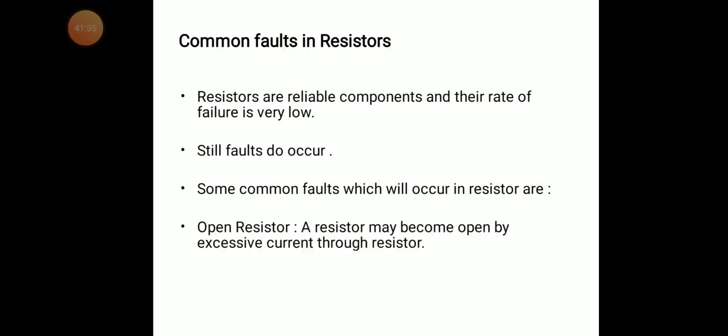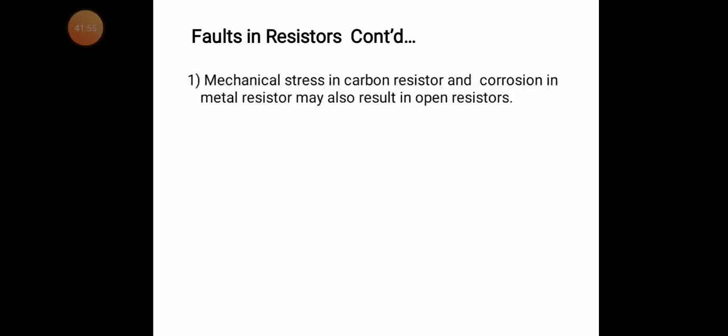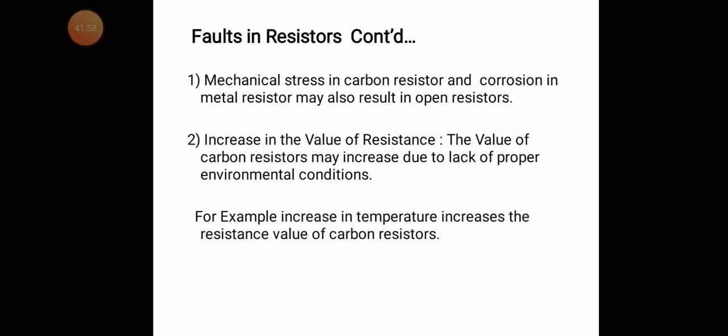Some common faults which occur in resistors are, first, the open resistor. A resistor may become open by excessive current through the resistor. If you pass excessive current through the resistor, it may open. That is called an open resistor.